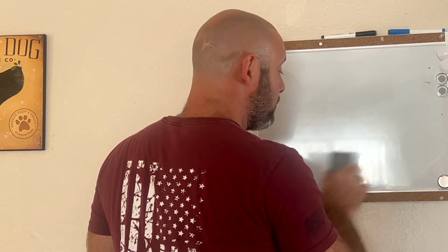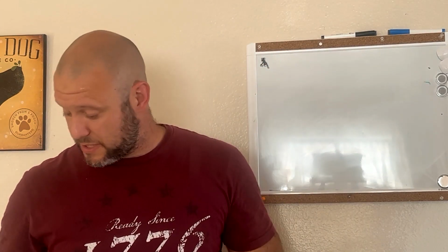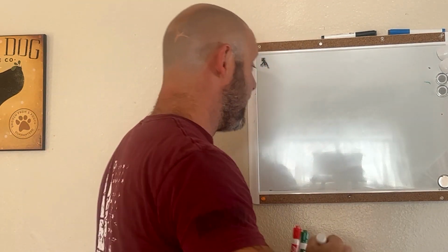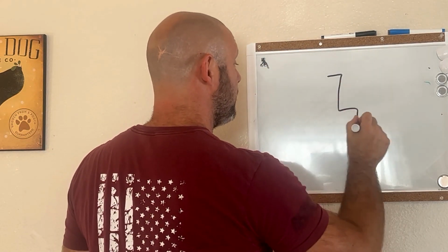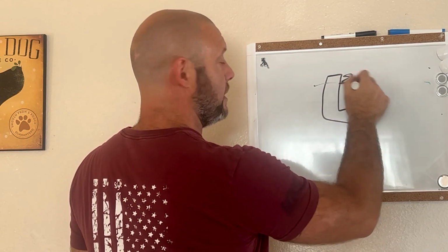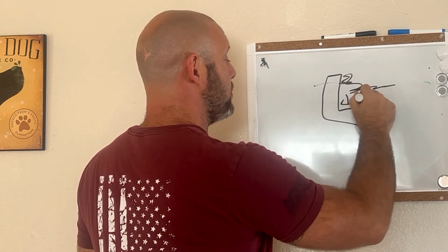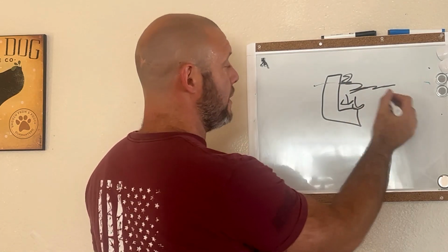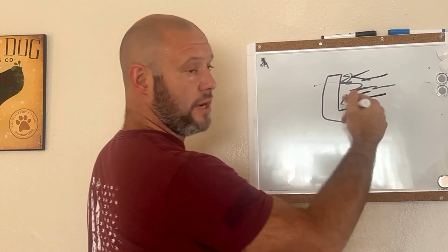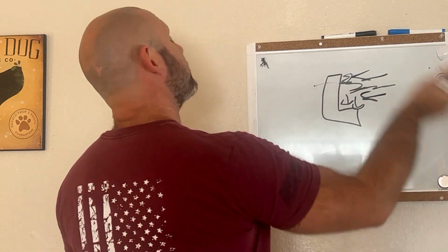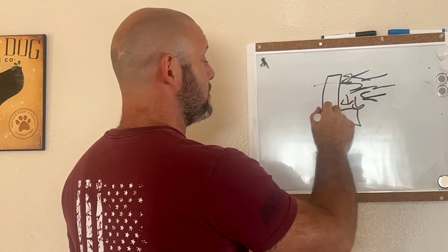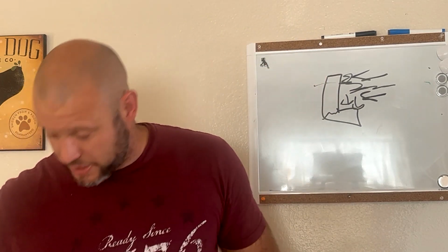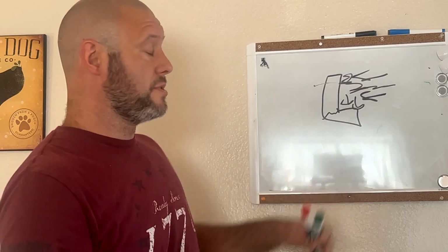If it's too much lateral earth pressure, you could do cellular concrete, but that adds a lot of weight down on top of that L-shaped footing, right? If I inject a bunch of lightweight concrete over here, that's pushing down on this. So I need to find a way to push down on the stabilizing section of the footing without pushing against or increasing the lateral earth pressure that creates the overturning. Especially if this breaks, you're screwed, right? So that's another very real concern. Like, there's nothing you can do that's going to solve that.